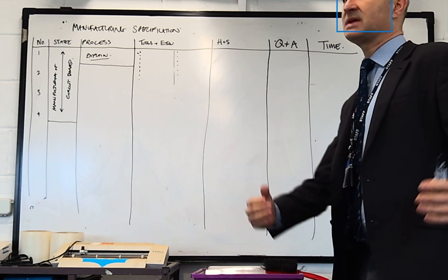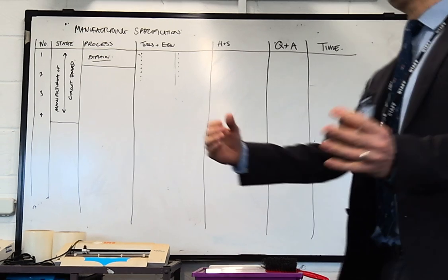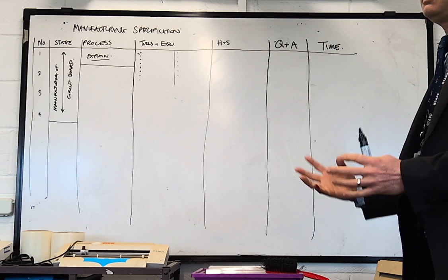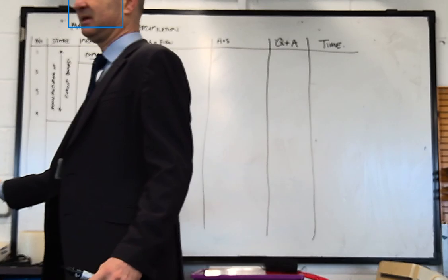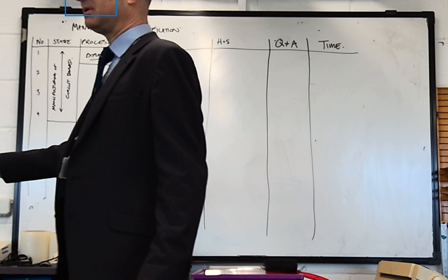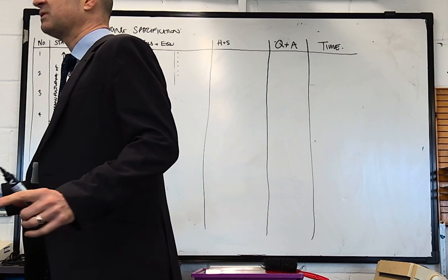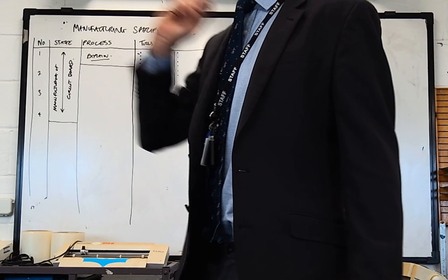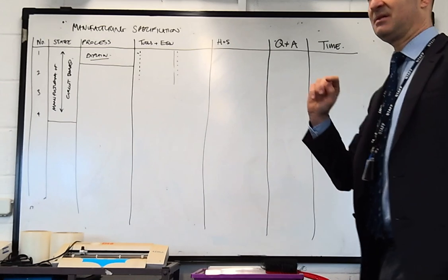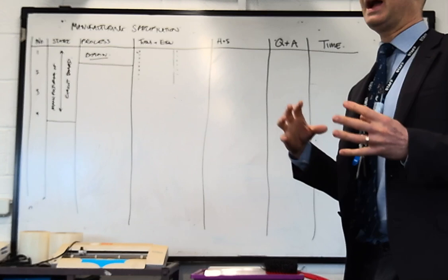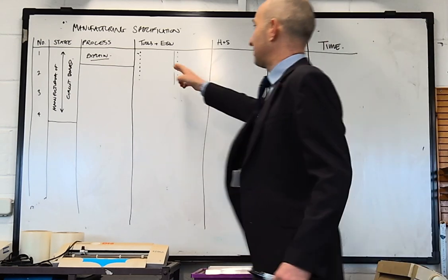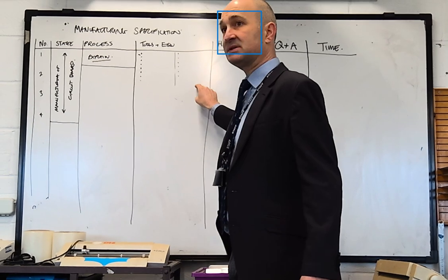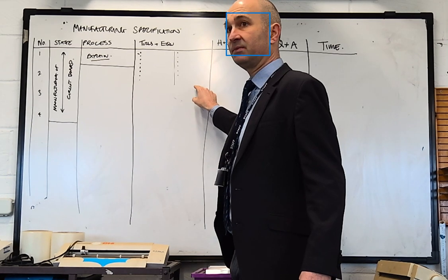So that's why I say, for example, printing out the circuit board onto a piece of acetate, which is a really simple step, and then putting it in the right box, okay, and developing the image onto your PCB. If you're going to do that, you've also got to put into it the cutting down the PCB. So we've got all of those together, really simple things to talk about, and also a really simple equipment list and tools list. Are you with me so far?